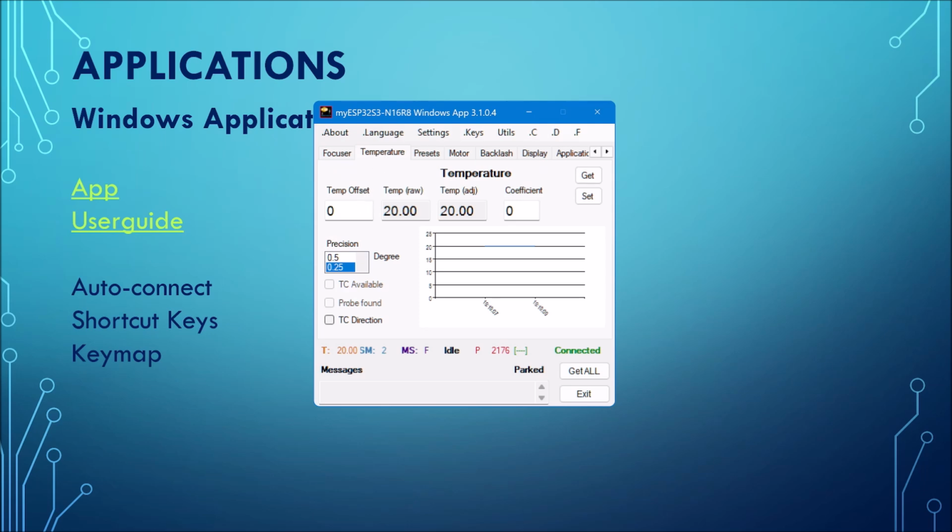The temperature, you can adjust the temperature, so if it was returning like 20 degrees but it was actually 19, you could go -1, and that's the way of adjusting the temperature. So if I do that and go -1, okay, that's fine, set this. So whenever you want to change something, the last button you click is set.